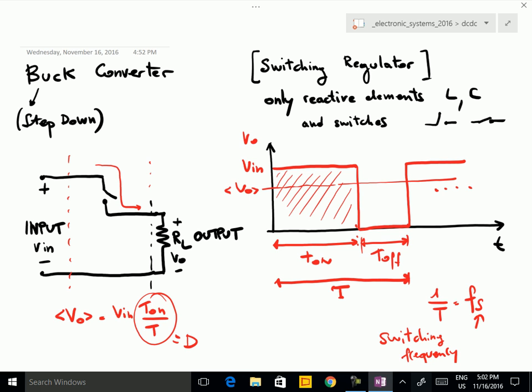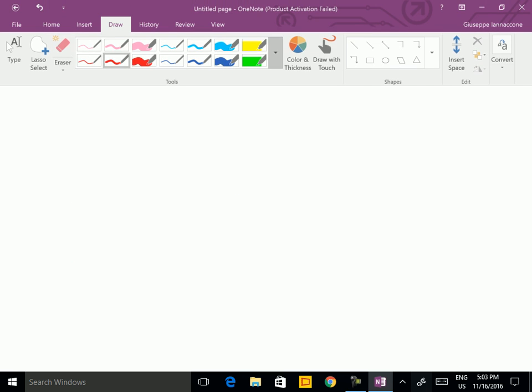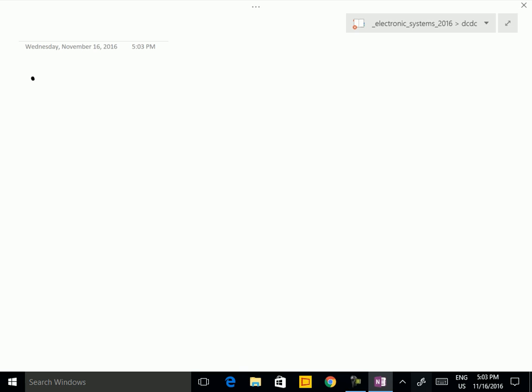You can have an excessive voltage on the switch during the switching, during turning off, that typically causes damage to the switch. So we do not want to stop instantaneously the current through the load. Well, there's no reason to do that because actually here we want a constant voltage in principle. So we need to change a bit the circuit while keeping the most important aspects, and this is actually what we do.